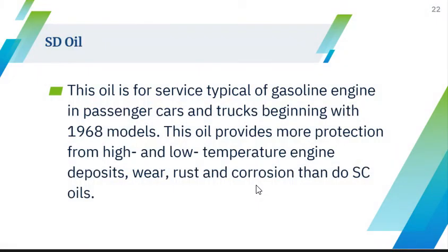We also have the SD oil. This is for service typical of gasoline engines in passenger cars and trucks beginning with 1968 models. This oil provides more protection from high and low temperature engine deposits, wear, rust, and corrosion than SC does.